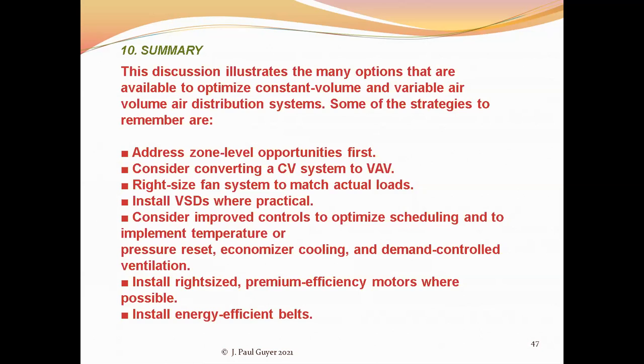If you do not already have it on the system, definitely consider installing an economizer, and possibly, if the occupancy load in the building changes quite a bit throughout the day or the season, perhaps installing a demand controlled ventilation system.